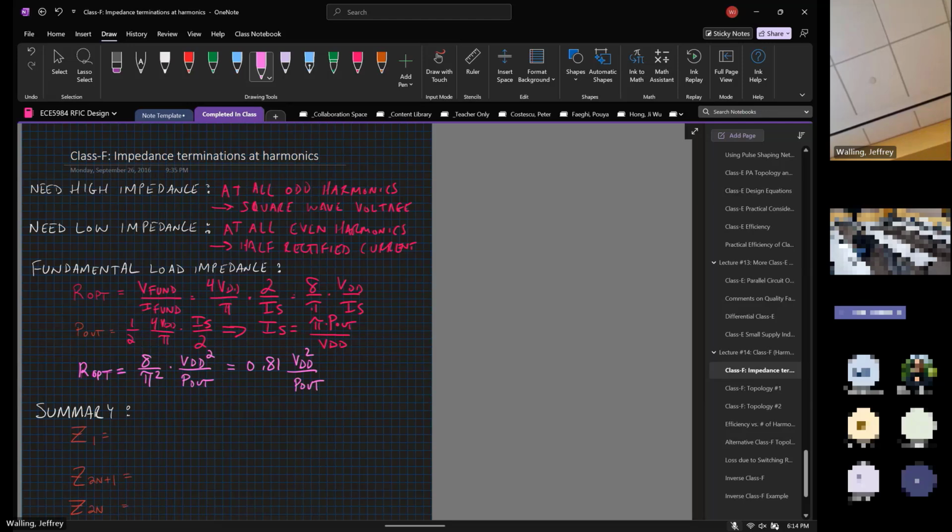All right, so that's pretty good. Is that better or worse than a Class E amplifier? Series ones. Better than the series, worse than the parallel circuit, right? So we have a factor that's greater than 0.577, less than 1.365. So pretty good. Better than any linear amplifier.